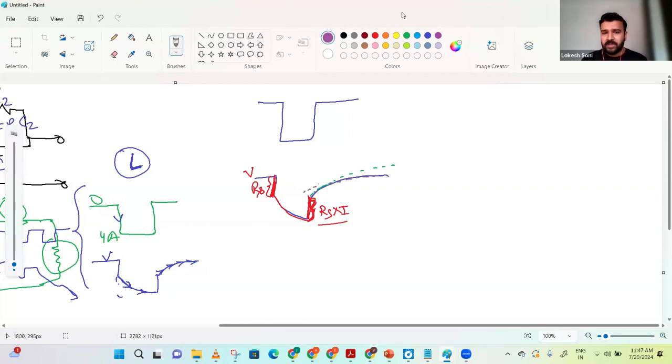It is actually quantified through the time constant concept. The faster dynamics help you derive R1 C1, and the slower dynamics help you derive R2 C2. The y-axis is nothing but R1 plus R2, and then this time constant concept helps you derive the C values. So this is how you derive RC values through the test. You put your battery pack or cells under test, and then you get this data and derive RC values. Parameter estimation is happening here. I hope it is clear.